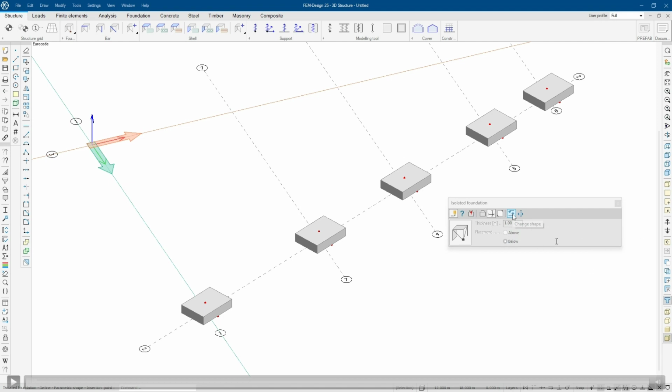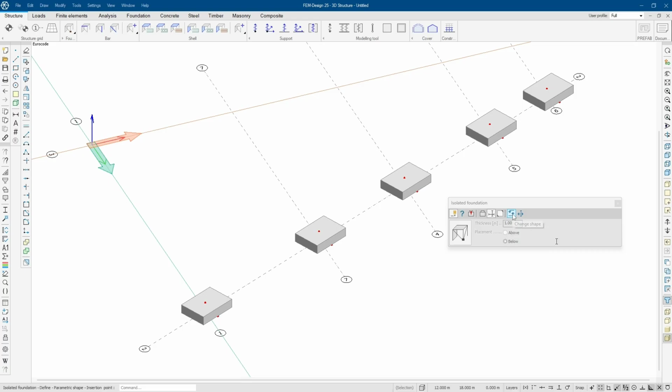There's a question: can the same parametric sections be used for both steel and concrete? Yes, it doesn't tell you what it is. You can even do timber. It's just a shape, and the same applies to parametric solids. You can do whatever you want with them. The parametric section module does not tell you what the material is. They are just like geometric shapes. They don't have any material properties whatsoever. Okay.